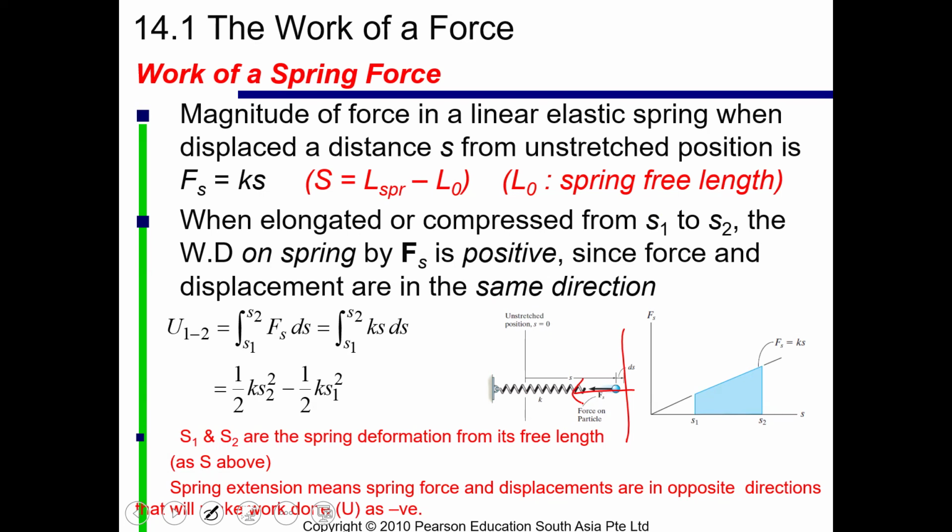Yes, students. Displacement will be negative. No, I'm asking about the work done. Because in order to evaluate whether the work done is positive or negative, you need to see that both displacement and the force in the spring are in the same direction. So in this case, the S is also like this, right? It's in compression. And the force in the spring is always pulling like that because it already was in the stretched position and now it is going back to its original location.